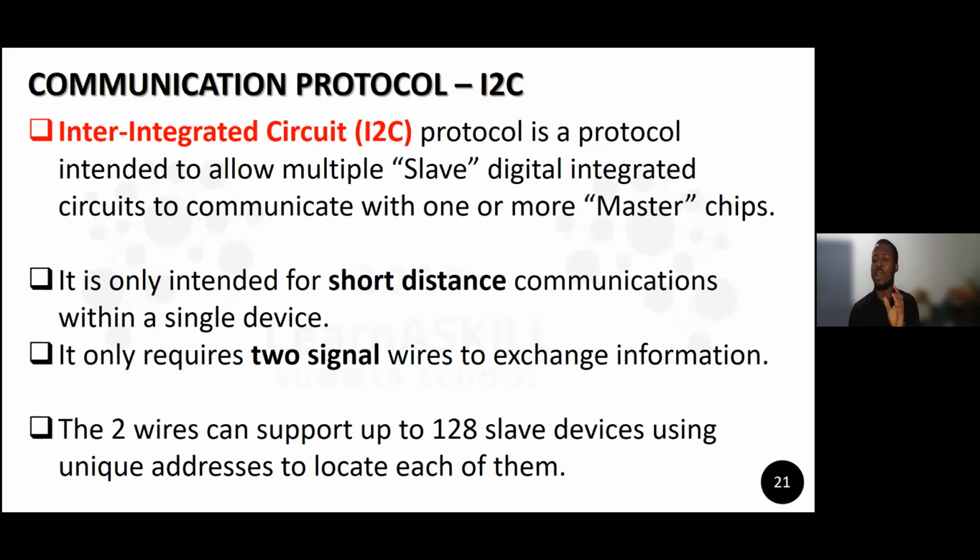Technically not at a time, but it gives you the ability to connect up to 120 devices to the Arduino and speak to them one after the other. That means you can actually create an Arduino supercomputer by just joining many Arduinos together via I2C, okay?